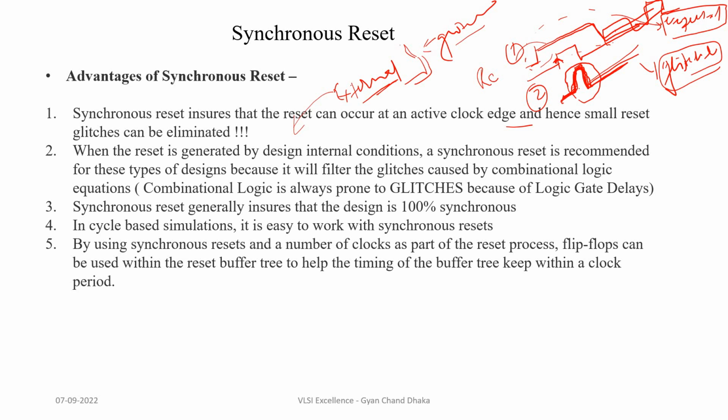Similarly, if we do not have an external reset and the reset signal for our other flip-flops is generated internally, then also using the synchronous reset we can make sure that any glitches generated by the combinational logic are handled. Suppose this is our internally generated reset signal, and we have something like this, A and B, and the AND gate output is the reset signal.